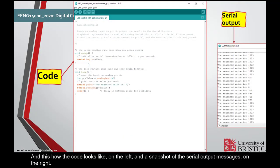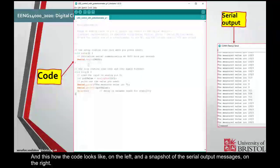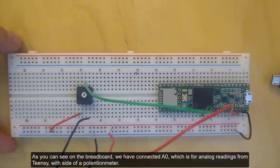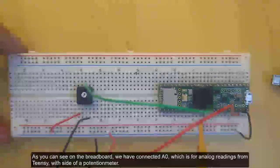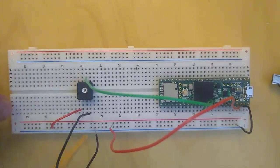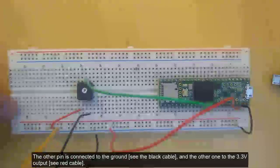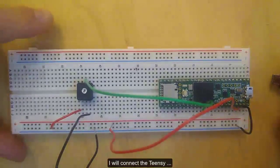And this is how the code looks like on the left, and a snapshot of the serial output messages on the right. As you can see in the breadboard, we have connected A0, which is for analog readings from Teensy, with this side of the potentiometer. The other pin is connected to the ground and the other one to the 3.3 volts output. I will connect the Teensy.